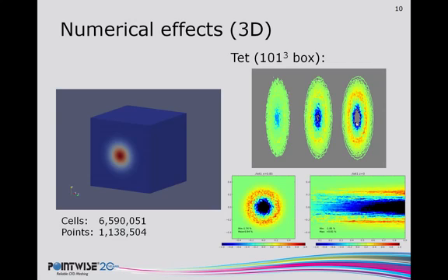The point of this is not to cast doubt on unstructured grids and unstructured solvers in general. In fact, many commercial codes contain more sophisticated algorithms that help mitigate these numerical errors on unstructured grids. Rather, the point is simply to highlight the tendency for tetrahedral grids towards numerical diffusion and to showcase a specific tailor-made example where the unstructured grid does not do an adequate job of resolving this sharp gradient. This is just kind of a best practice sort of approach.